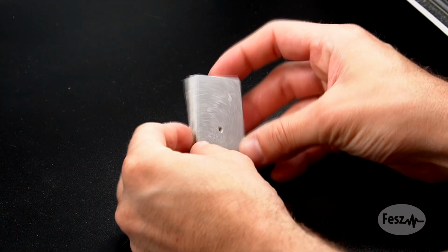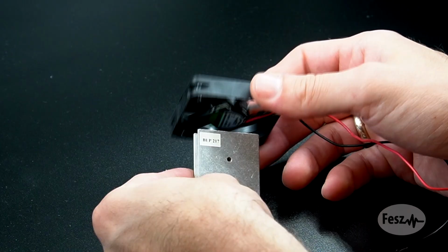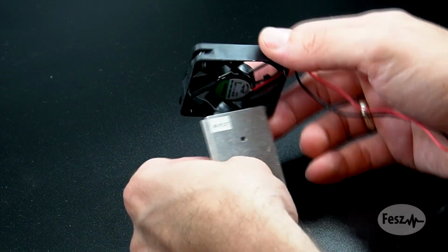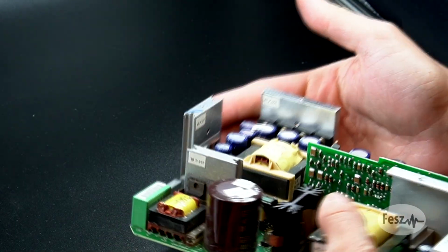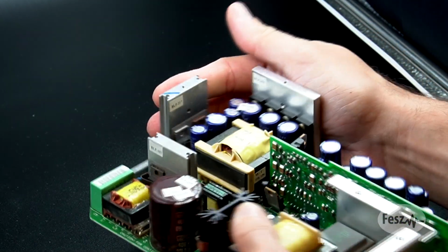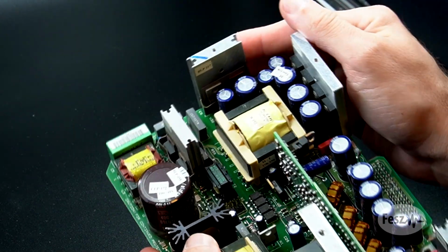Now, the main limiting factor in this sort of model is knowing the exact thermal resistances of each heat path. While the datasheets do provide some information, these values are usually extracted under some very specific test cases. For example, this heatsink will have a completely different thermal resistance if there is airflow around it, or on the other hand, if it's inside of a cramped box with a lot of other components.